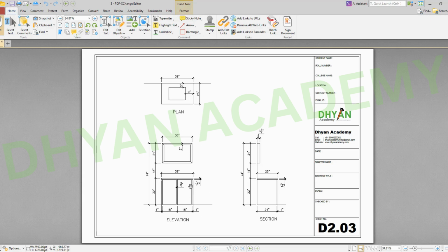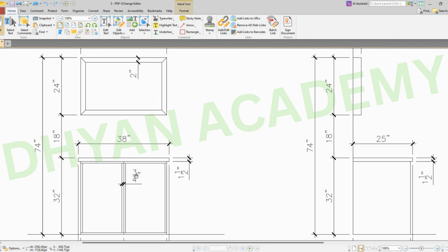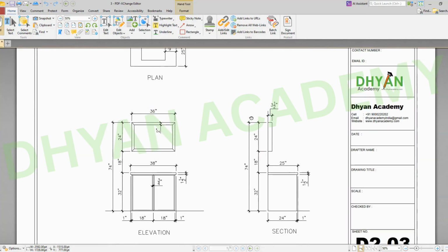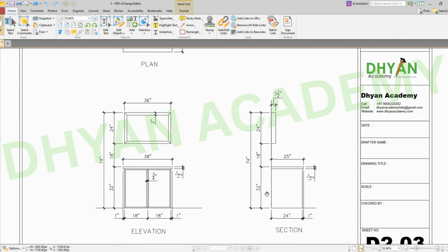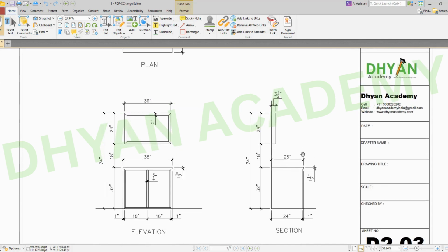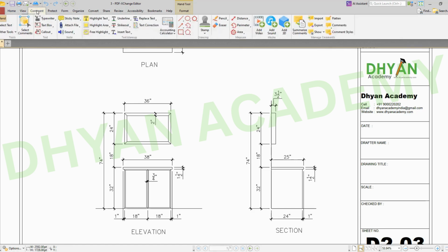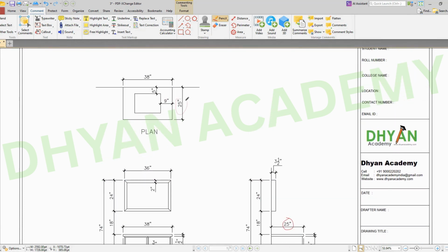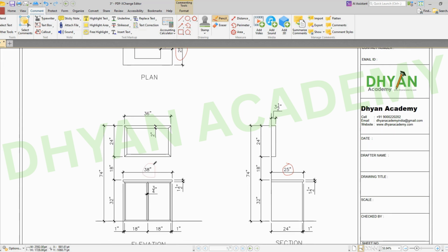What is matching here is that this width of 38 should be in the plan as well. I see here I have the 38 inches. Similarly, if I go to this section, the depth has to match again with the plan view. So 25, and you see you have 25 here as well. Let me just mark it, so it becomes easier. I have 25 here, and if I come back, I have 25. Similarly, what I saw there, 38 inches, is the same 38 inches here also.